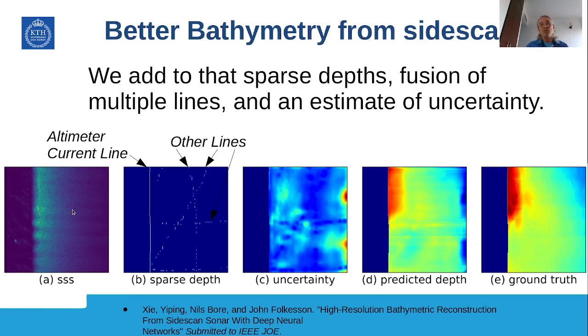And that's because we're not really pinning it in any way. It gets sort of pinned at the nadir, because we know how far below the vehicle this is, right? But over here, we don't really know the angle. The angle could be drifting up or down somewhat. So in order to fix that, we used, like I mentioned already, the altimeter readings that we have. So here's the altimeter reading that corresponds to that nadir line. We could record that, and we make this second image. So we input this image and this image. And along this line, we have the numbers that correspond to the altimeter readings along the path.